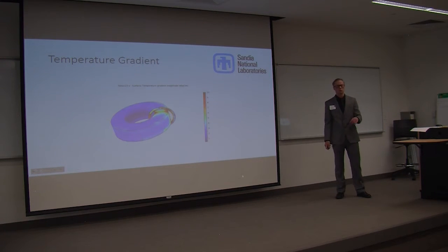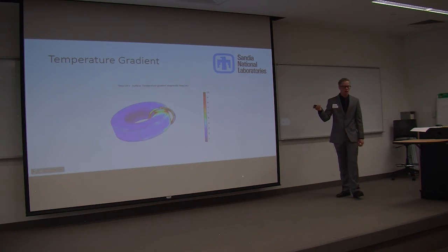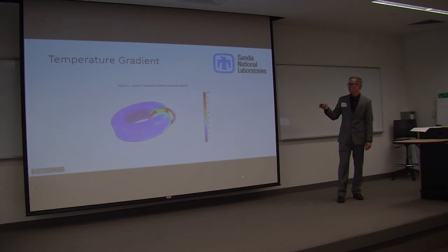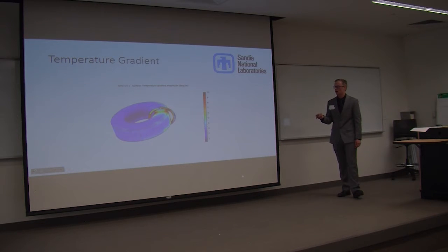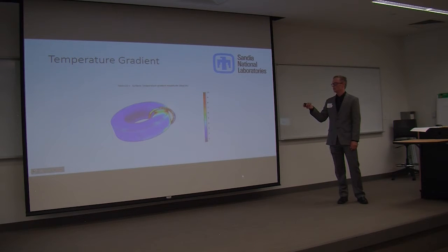The plot only changes by about 0.03 degrees. But the temperature gradient is kind of interesting because we can see where the coil is. We have a much higher gradient of temperature, and that's just because copper has a higher conductivity and heats up faster than the ferrite.